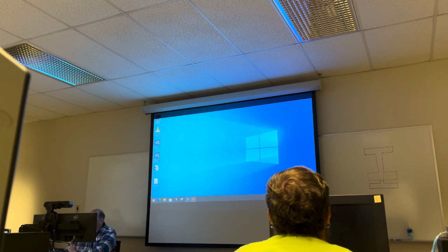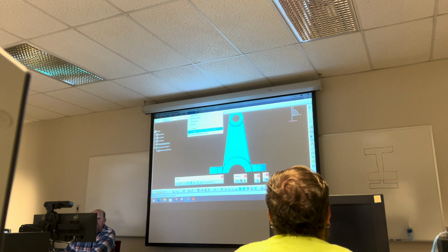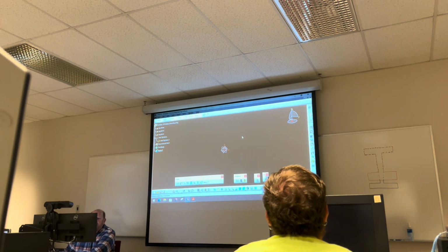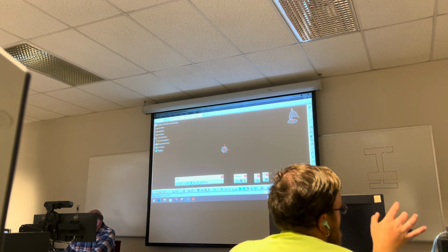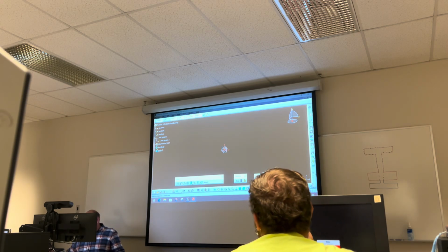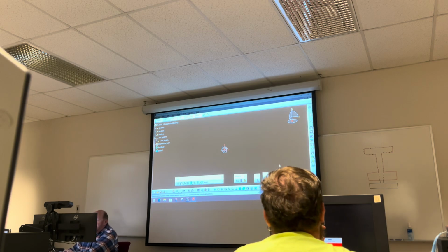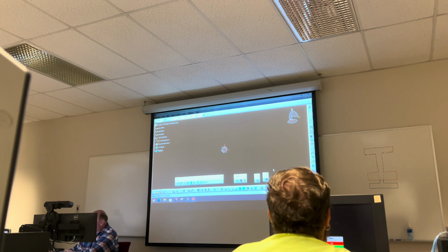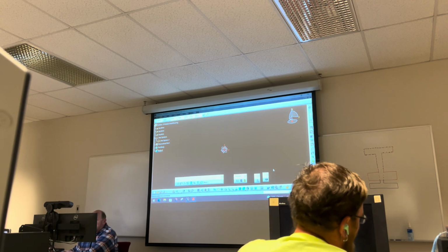So with this part, go back over here. Remember, this part's in English as well. So when you start up, if you've been doing metric models, which those other two are, make sure that you switch over to English, because you might get halfway through the part and have to switch over, or you'll try to put a fillet on it and it won't work.